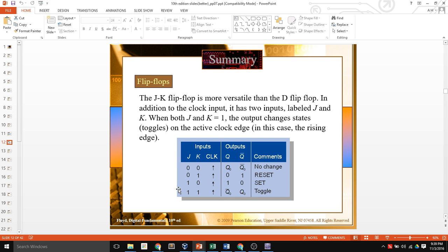Now, with an SR latch, we have this invalid case. We have a 1, 1 for S and R. And that actually gives us something that's impossible to understand what's happening there. We can't trace what's going to happen when you do that. It just oscillates in a few nanoseconds. However long it takes to iterate through those gates, those signals are going to oscillate very quickly.